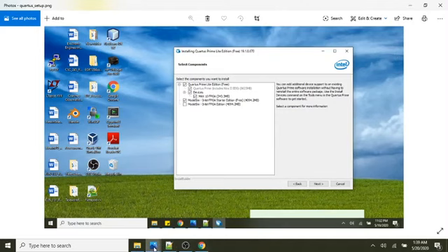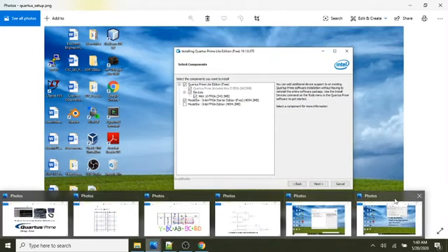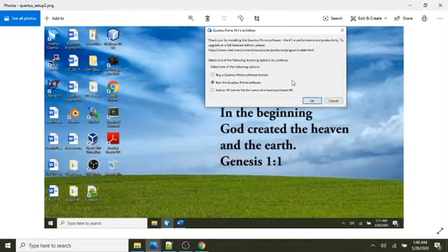The other thing is when it's finished, when you launch the software, you want to make sure that you select Run the Quartus Prime software. You don't need to buy a license or add an IP license. So just make sure this radio button is selected, Run the Quartus Prime software, hit OK, and you may have to double click the Quartus icon.